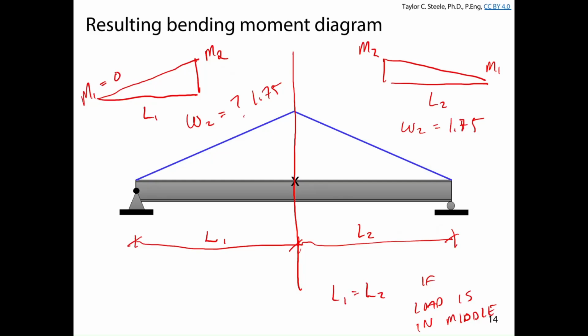We're also going to increase it by reducing the unbraced segment length to L1 instead of the length of the girder. So if you encounter a girder with a single point load, omega 2 is going to be 1.75, and then you just use half the length of your beam to calculate the value of Mu.